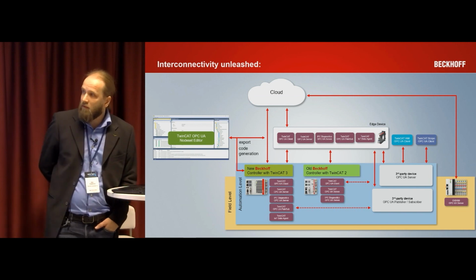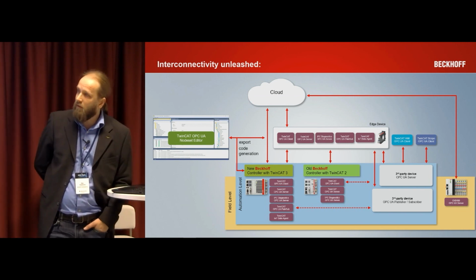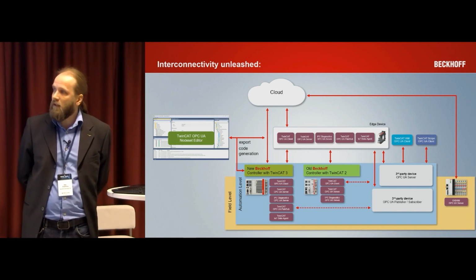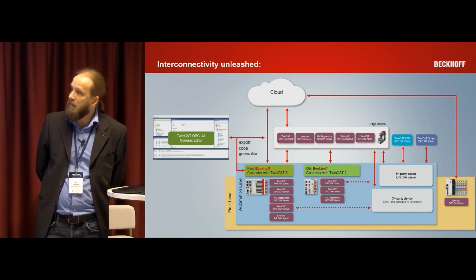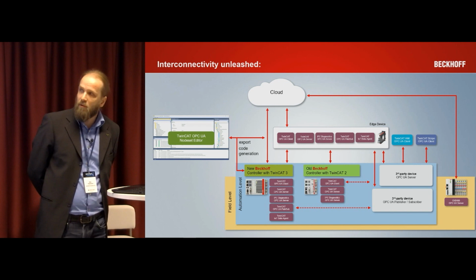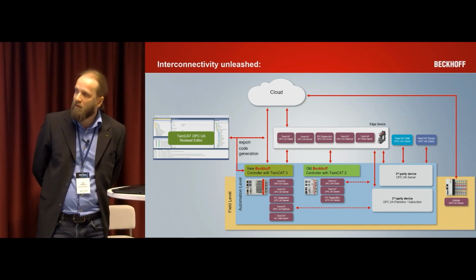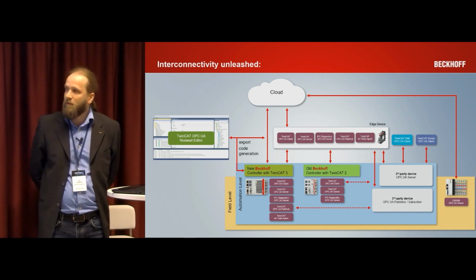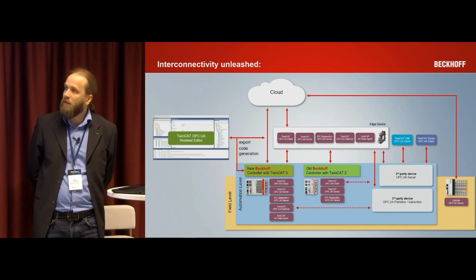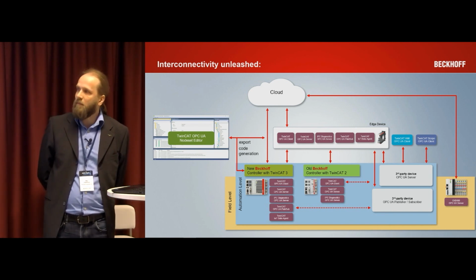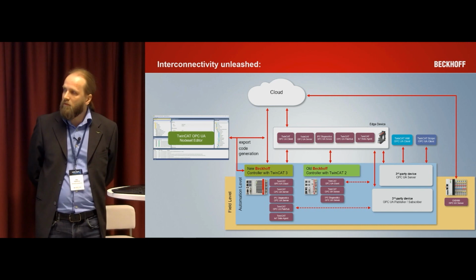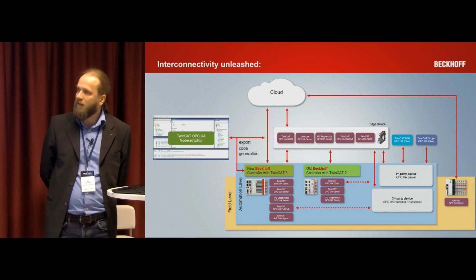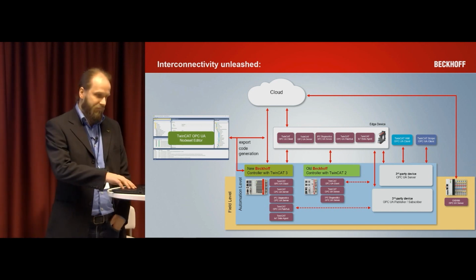And there you can see how the NodeSet Editor software integrates into the architecture picture. So it's on the left side of this slide. And there are arrows going both ways, so it means both importing the data and variable mapping information from the PLC, but it also provides producing the PLC code for making the OPC UA interface easy to implement in the controllers.